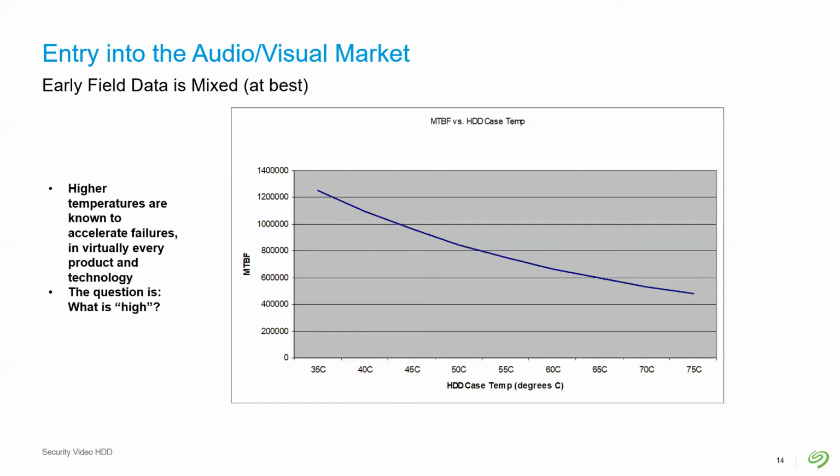This slide should open your eyes a bit to the fact that you can degrade reliability by having things run at higher temperature. Important to note, that's not a hard drive thing. In fact, if you work in reliability, you know that warmer temperature is a failure rate accelerator that is accepted in every form of reliability demonstration testing for almost any product all the way around the world, from tires to popsicles to rubber baby buggy bumpers. If you're testing something for reliability, you can use higher temperatures as an accelerator. And as long as you can control the temperatures, it's easy to measure what that acceleration is.